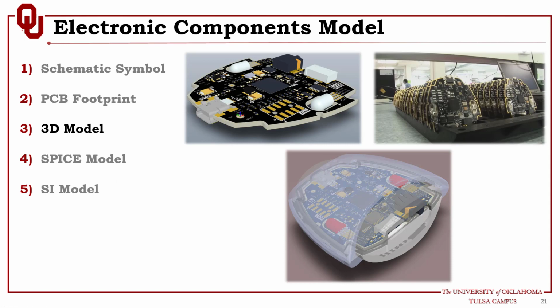Usually the ECAD engineer designs the board in 2 dimensions and sizes it according to the positioning of the critical elements in the case, using dimensions provided by the mechanical engineer. Once the board is done, it will be sent to the mechanical engineer. The mechanical engineer will try to fit the actual physical board into the enclosure. Now, it might not fit, the clearances might not be right, and we might have a lot of problems. To help avoid mistakes and that multiplier factor on the cost, we need to have a 3-dimensional ECAD and MCAD design environment where you can collaborate between the mechanical design and electrical design before you build your board. This will save a lot of cost.